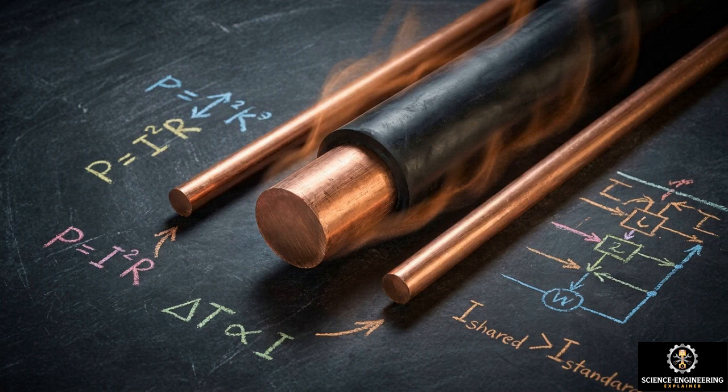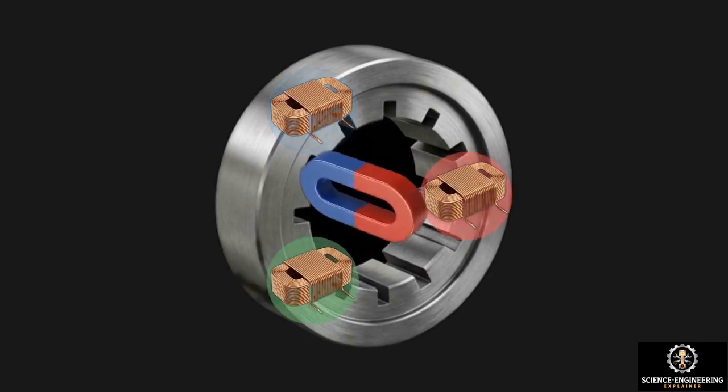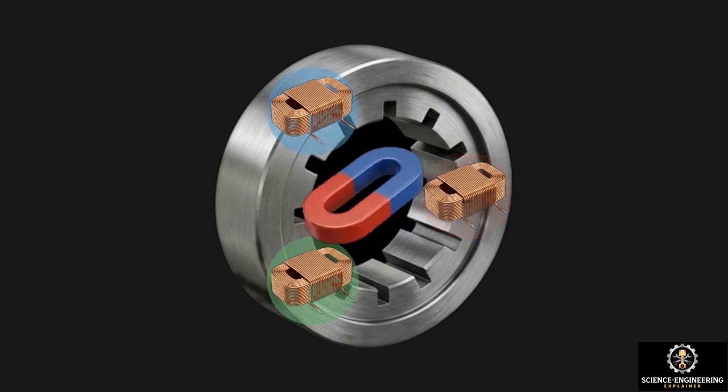Safely managing these overlapping currents requires a disproportionately thick shared wire, which limits the potential savings in copper or aluminum. Two-phase power solves the mechanical problem of rotation, but the requirement for 4 conductors makes it economically inefficient for long-distance distribution.